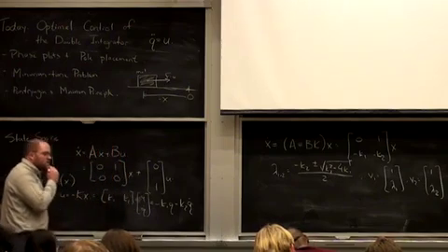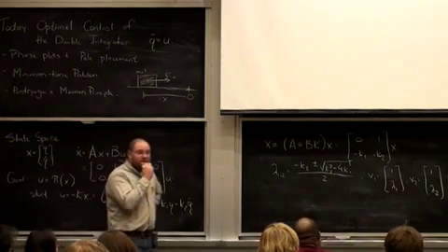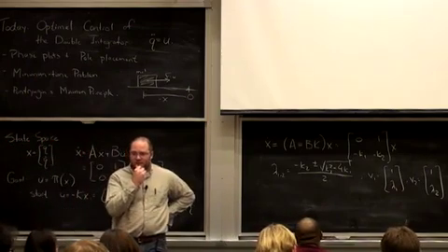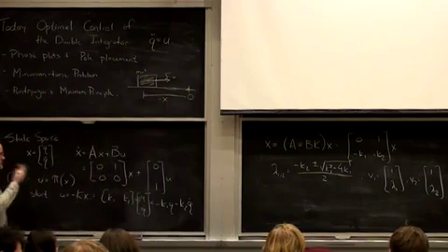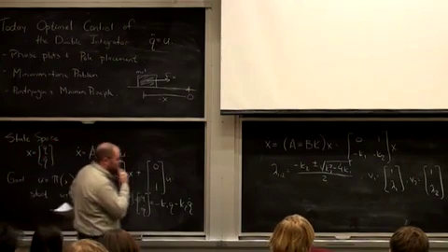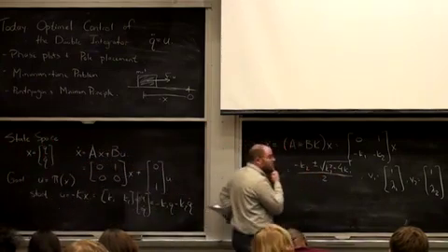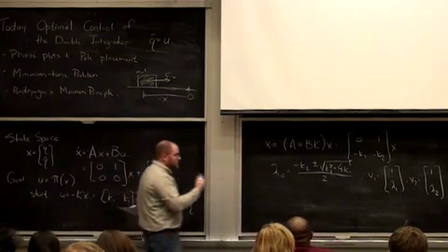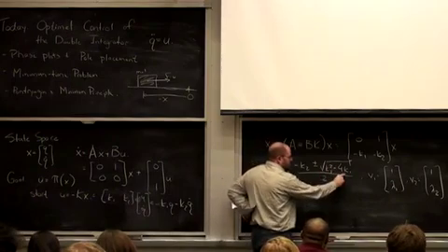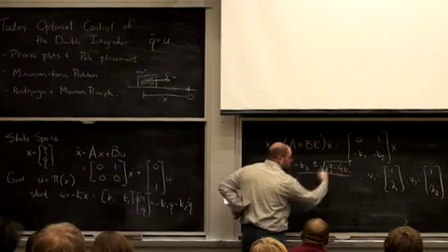Okay, so what are the conditions on the eigenvalues to make sure the system is stable? You want them to be both negative, okay. And potentially we also care about whether the system has any oscillations or not, which manifest themselves in whether we've got complex eigenvalues, right? This is all things you've seen in plenty of classes, but the only way it's going to be complex is if this thing goes negative, right?